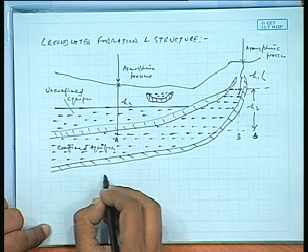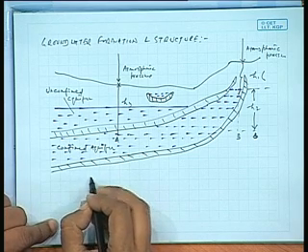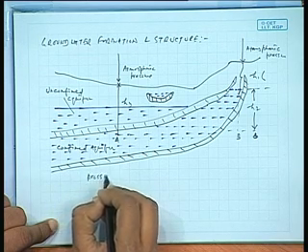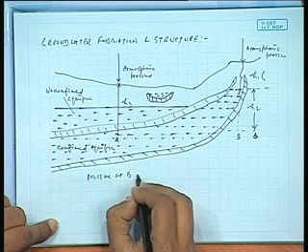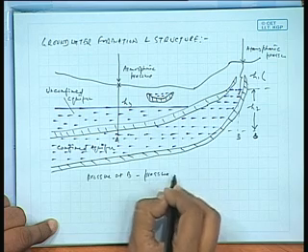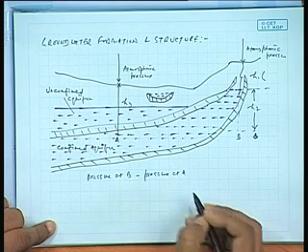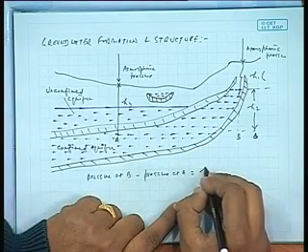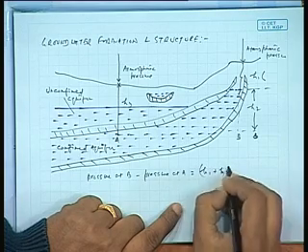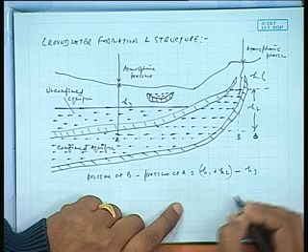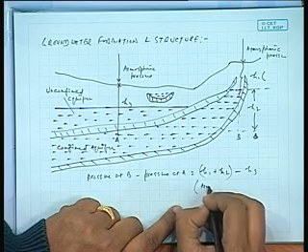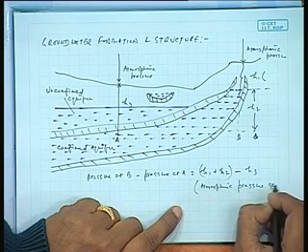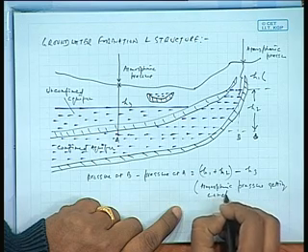If we compare the pressure here, we are making a difference of the pressure at point B minus the pressure at point A. You can observe that the difference is basically H1 plus H2 minus H3, with this atmospheric pressure getting cancelled, isn't it?